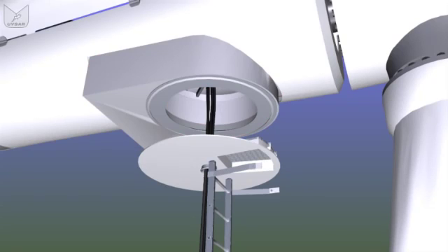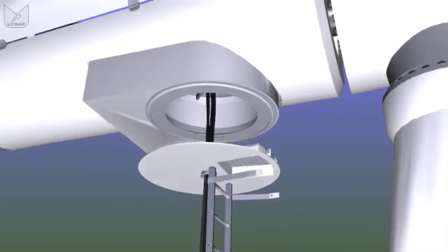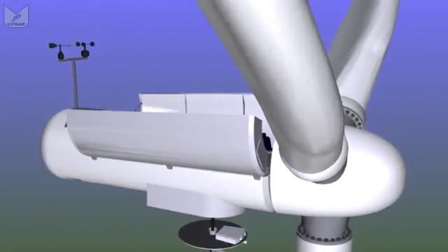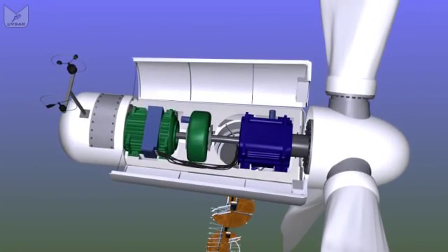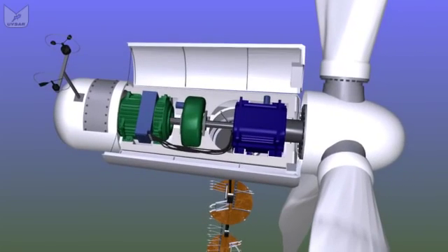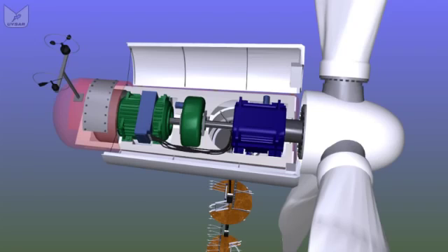And this sealed platform acts as a bit of fire protection, also avoids people falling back down the tower, because at the top of the nacelle we simply have a hole through which we climb. And the nacelle in this case is a vaguely tapered tube. At the back we have the wind sensors, which give us speed and direction and allow the turbine to face into the wind and to change the angle of the blades. The nacelle itself is just a fiberglass tube.